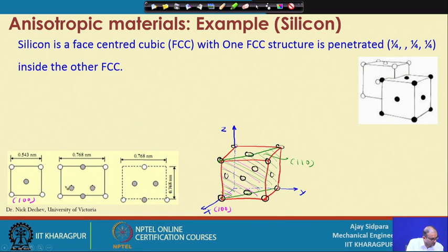So, it may cross this particular thing also. So, this is about the 110 plane. And what is this 111 plane? So, 111 plane is this plane. So, now let us consider your plane is cutting all these three. So, this is called the 111 plane, correct.